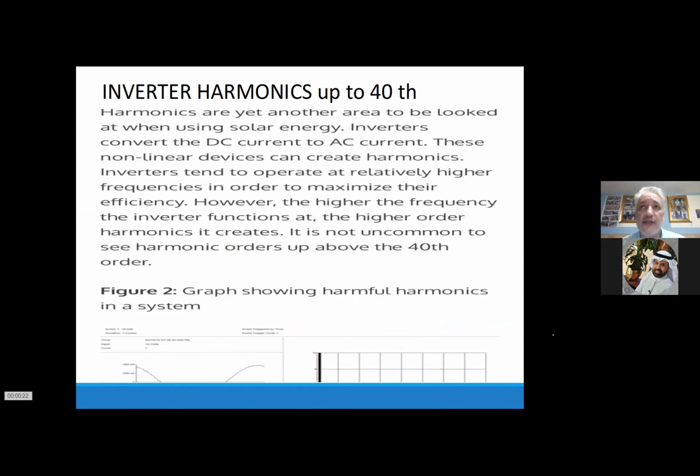So what happened was they had harmonics of 10 to 20% sometimes, and then off again, and differences in rainy and in sunny conditions. Once they measured the stray currents of the transformer and they didn't find one, they changed it, and then they saw that actually the cable was not connected.